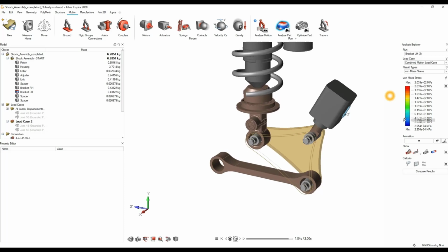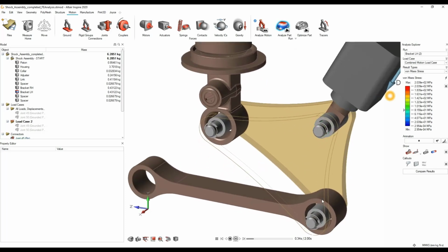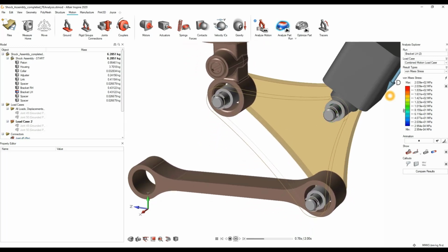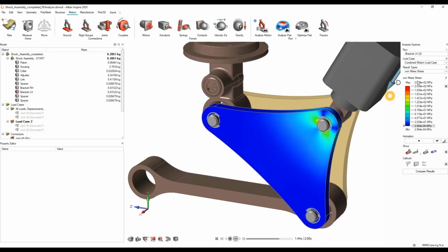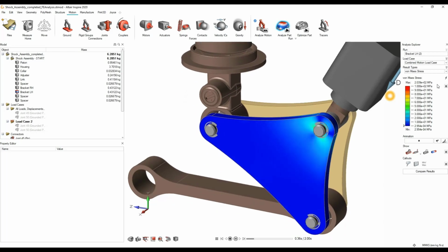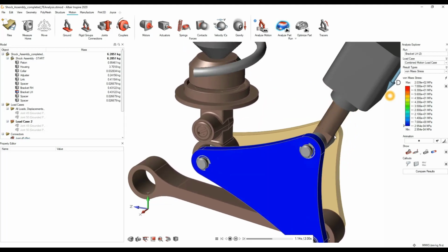And with this ISO slider here, you can slide it up to a certain value so that it will only show you the moments in the time frame when any of the relevant elements exceed that value of stress. And obviously you can change your maximum and minimum values as well. So if you change that to 100, then you can see more areas that are affected.